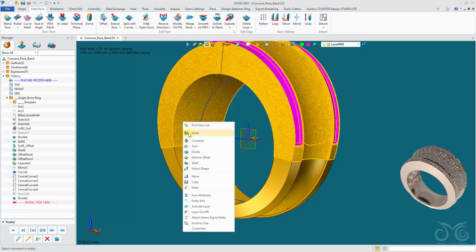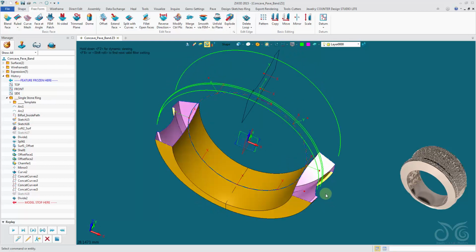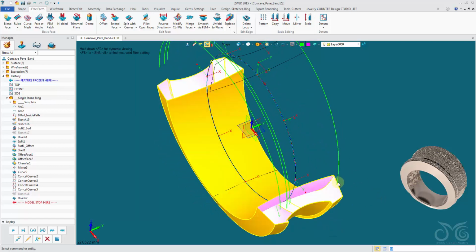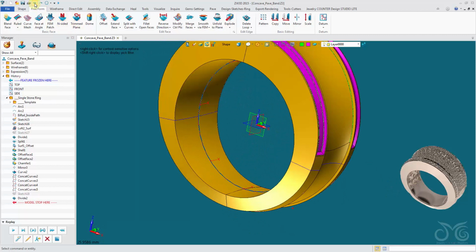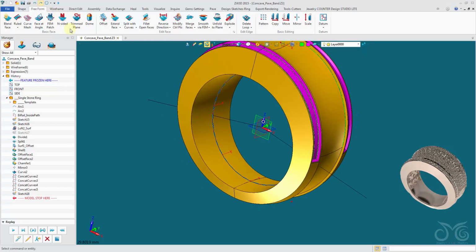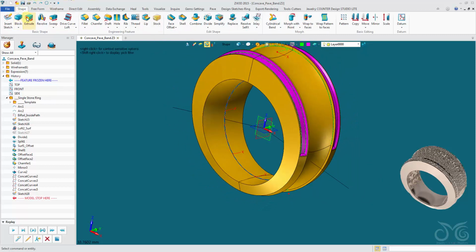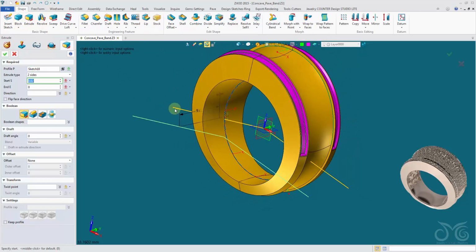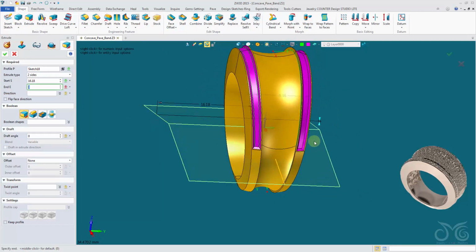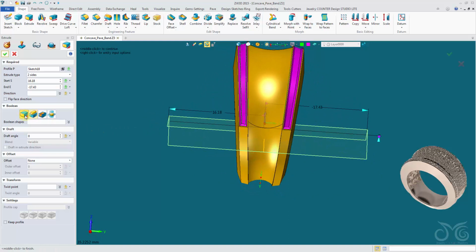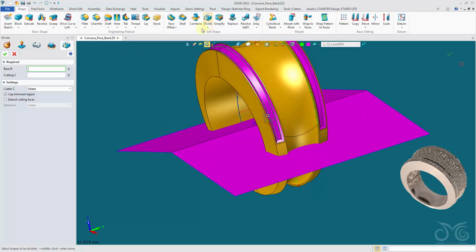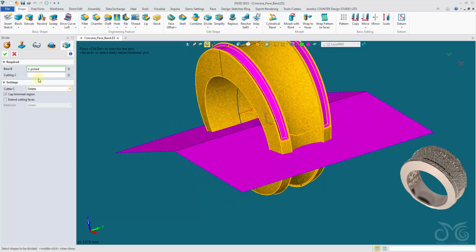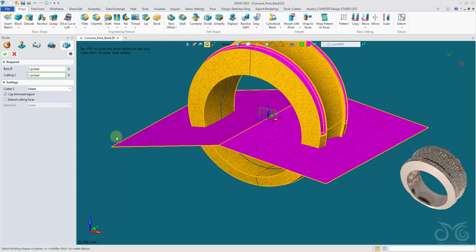However, I'll end up with no end caps, which I could come in and add with my end-sided face tool. However, instead of splitting with curves, I'm going to extrude this sketch as a base, and then I'll simply divide my ring shank to this extruded shape, cap the trimmed regions.